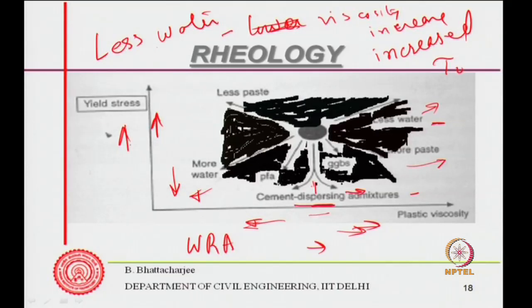Lower water means yield shear stress increases and viscosity also increases, and with more water you will have lower yield stress and lower viscosity. With less paste, viscosity reduces but the yield shear stress increases.